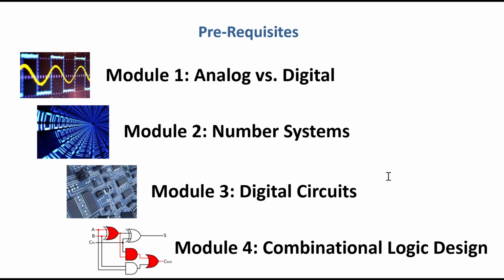So once we had all these basic gates in hardware and knew how to interface them, we started looking at combinational logic design. Combinational logic design is where you build circuits that produce a logic output, and it's usually just one bit based upon multiple inputs, so 2 inputs or more, but they were more complex than a basic gate. So instead of an AND gate that had 2 inputs, you might build a circuit that could implement any arbitrary truth table, 3 input, 4 input, 5 input truth table, and we learned about how you actually synthesize the circuitry to produce the desired output.